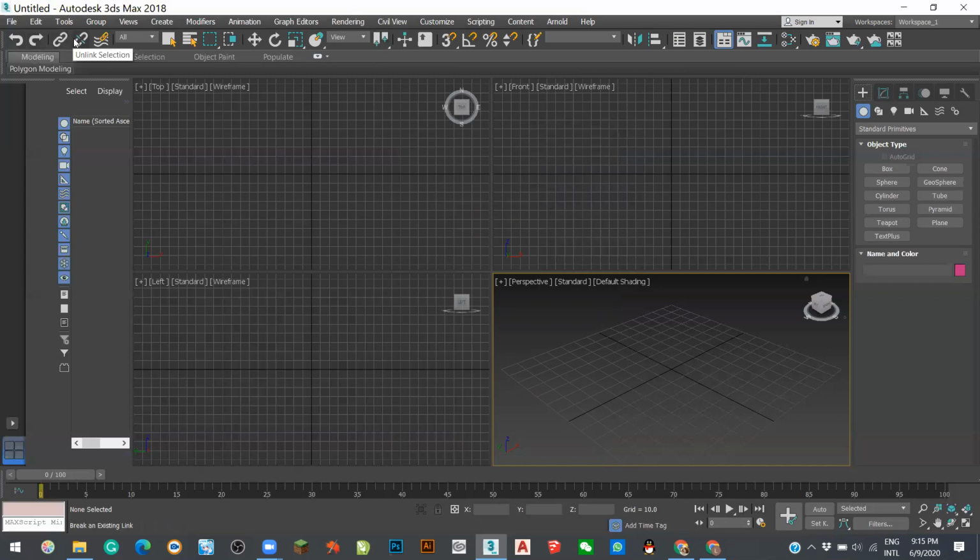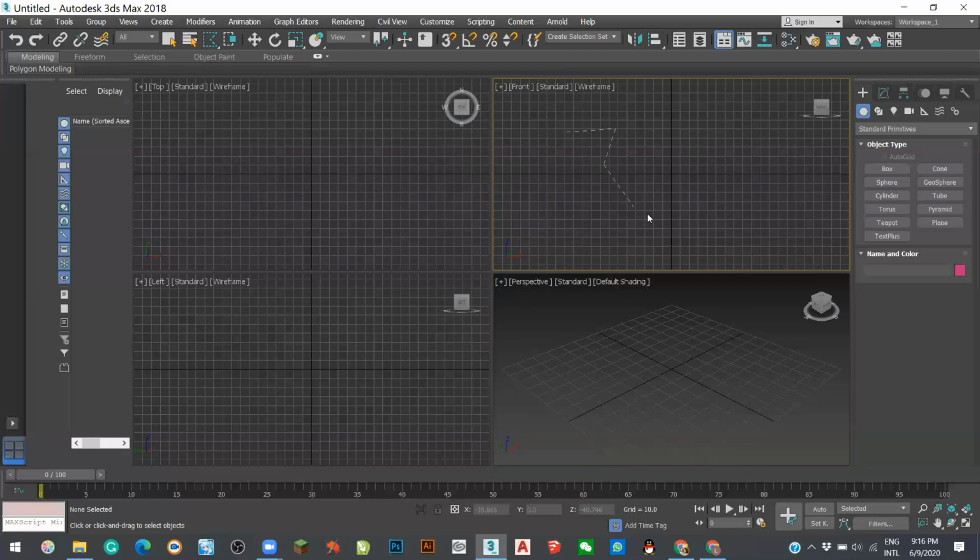Then after that, this is the main toolbar. This is undo, redo. This one is link for your image. This one is select. When selecting, you can type Q also. You can see this one will change to a circle, and type Q one more time, it will be the fence selection, and one more is freehand. This is the lasso selection, and this is the rectangle. So I type Q for selection, and it will be like this, and one more will be like this.